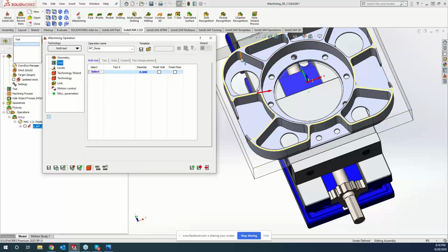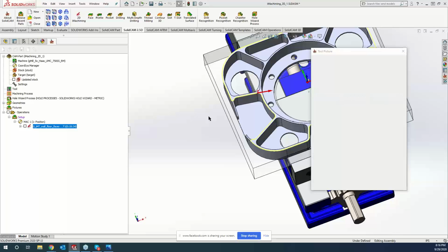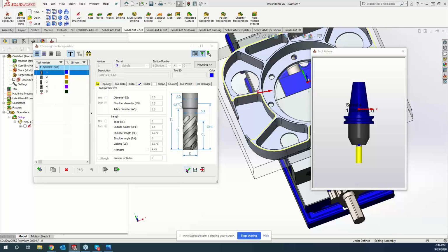But as soon as I pick my tool, it will automatically know that I only have extra material in these key locations here. So let's grab that tool now. Hit the green check mark. And you'll see this final updated stock calculation pop up when you're grabbing that tool, and that's the preview. It's going to be that blue color in there. Plus, it's figuring out the best toolpath right now, so we're not wasting any time cutting air or recutting anything we've already done previously.